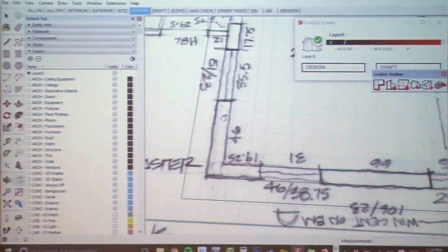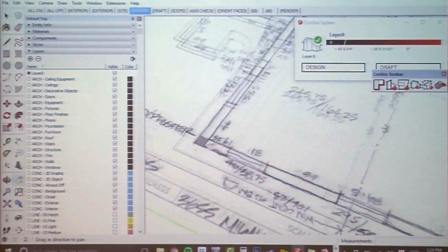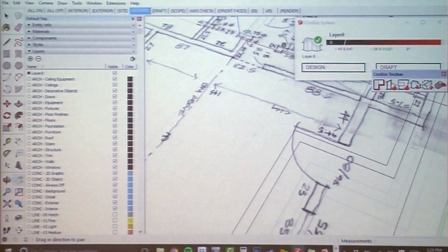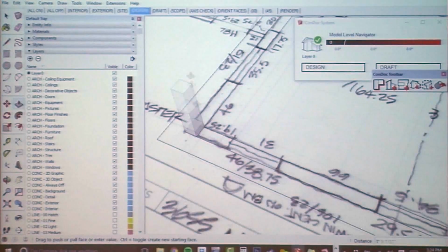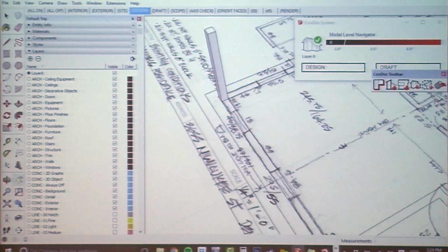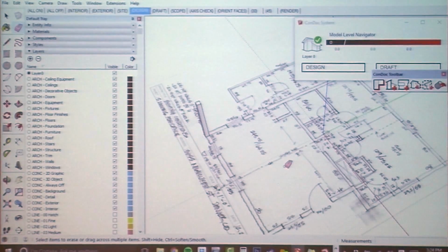And I'll start on this bottom left corner here and draw a square. So that is an 8-inch by 8-inch square. And then I'm going to pull it up by our ceiling height. So here I made a note of 94.5. So I'll use my push-pull tool and pull this up by 94.5. Enter. Okay, so now right here at this point, this other line work is really not needed. We've positioned that wall right where it's going to be, and we're going to grow this building off of it.